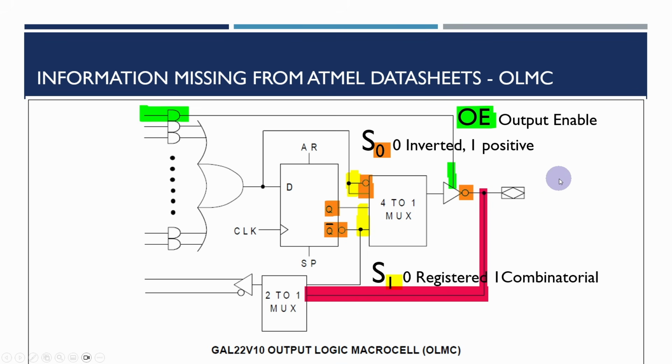It's just that I haven't come across, using the simulator before, needing to distinguish between the outputs and the inputs. When you've got an output, you need to put a high or low in your .si file. And when you've got an input, it needs to be a 1 or 0. And when you get the output errors in here, then generally, if you've got something which is high impedance, you may very well find you need to change a high or low to be a 1 or 0. Got to the bottom of that one.